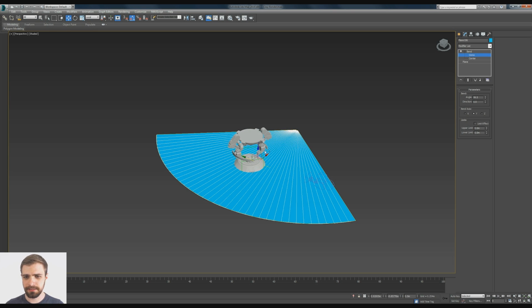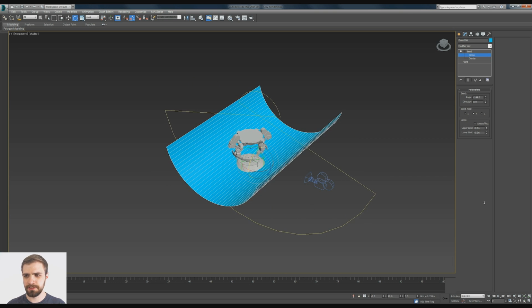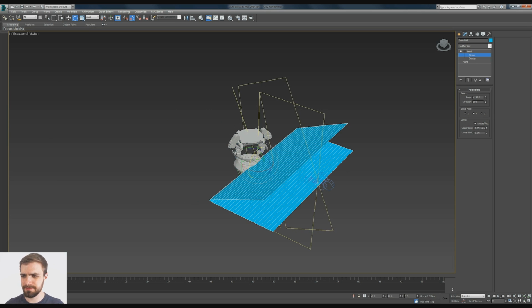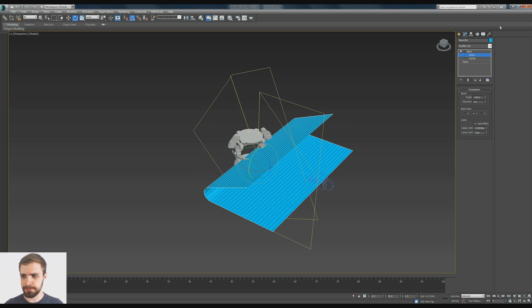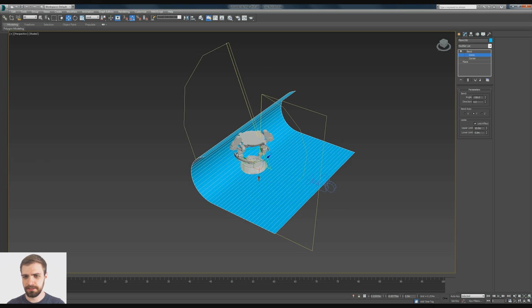Yeah, that seems close. So then I'm going to twirl down on the bend just to adjust the direction of this bend. Got the gizmo, got my rotation, and 90 degrees. Looks like it needs to bend the other way, because what we're doing is making it go from the floor to the wall in one continuous piece. So if we hit limit effect and then adjust this limit and drag that up, maybe like 10. Sure. They do the same kind of thing in photography.